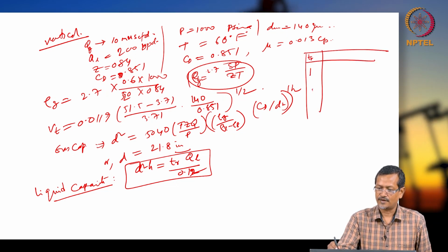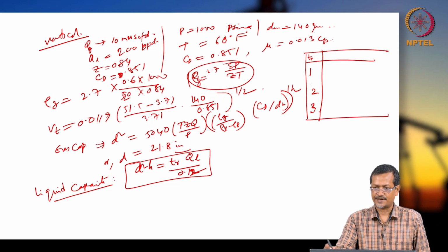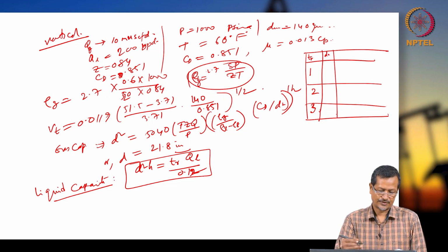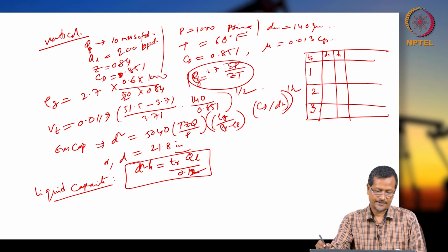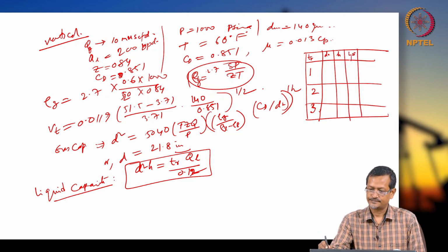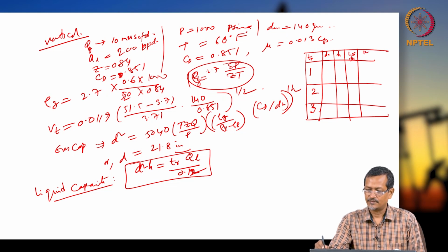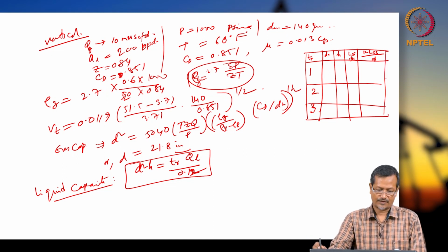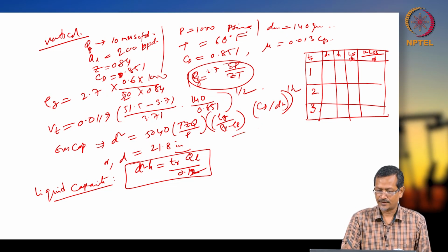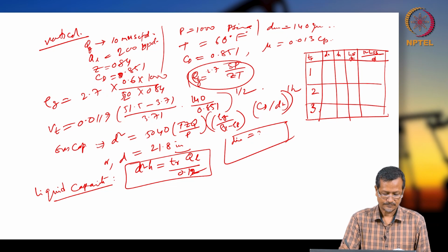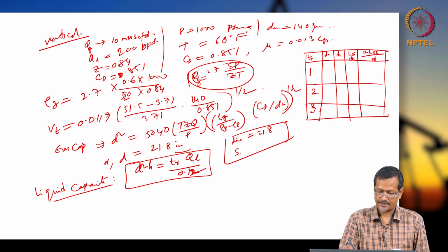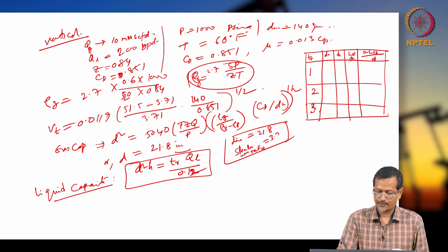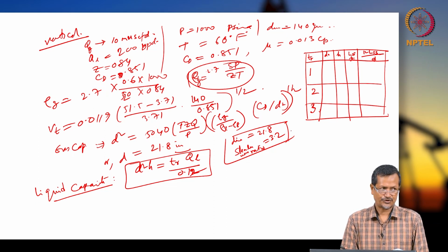Okay. So again you try to calculate TR, you take 1, 2, 3, different retention times, and then you can calculate D in inches, which you already have, H you calculate, LSS in feet, then 12 LSS divided by small d, or LSS divided by capital D. So if you calculate, then actually the diameter we are getting is 8, and slenderness ratio equals 3.2. Around 3 slenderness ratio means your design is okay.